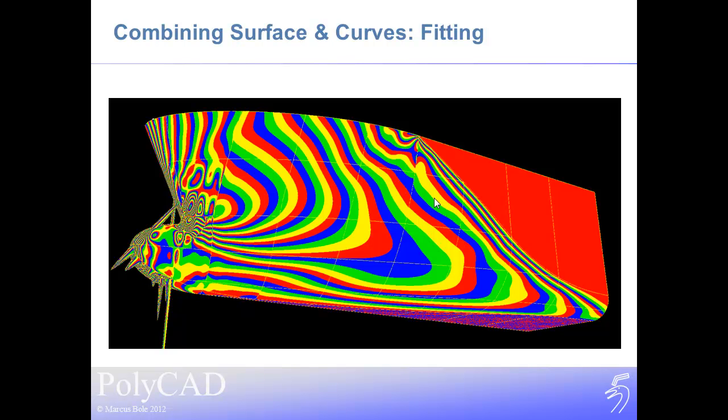So this is still a work in progress, still trying to identify the best ways of regenerating our surface in this area. One of the benefits of going through this process is that, although we can't see it very well there, a lot of the subdivision curves can be re-estimated, refitted to the lofting curves, and that means that we can improve our original estimate of this shape.